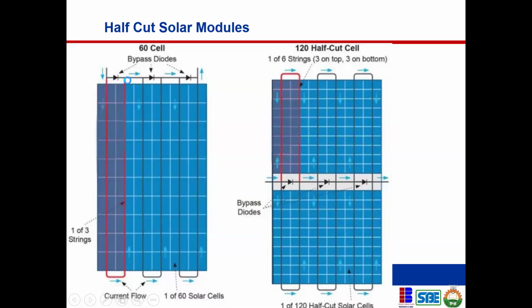Essentially, because of the way these PV modules are structured, there's what we call a bypass diode at the end of every arrangement, right? So it typically has 3 bypass diodes. So when there is a shading on one of these cells, it will reduce the entire output from this arrangement, okay? And then you have a much higher reduction in your energy output.